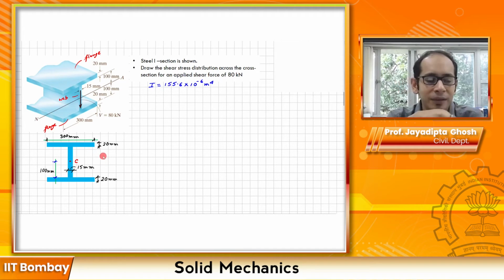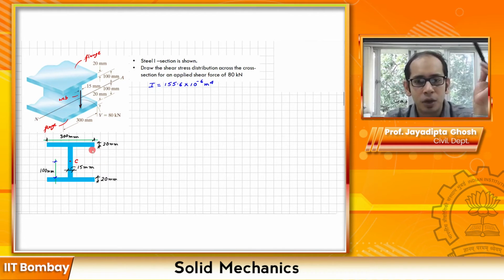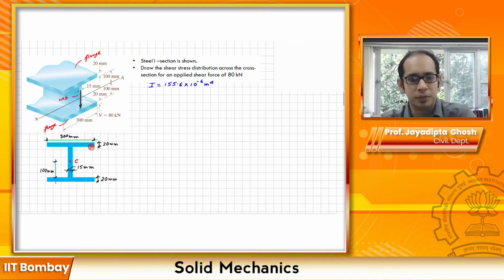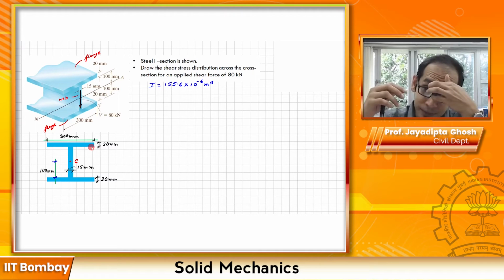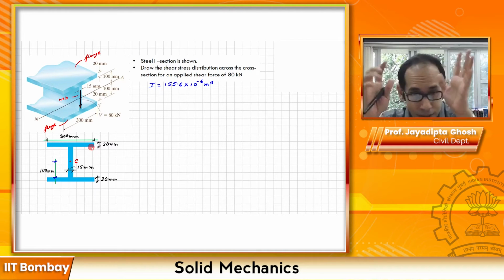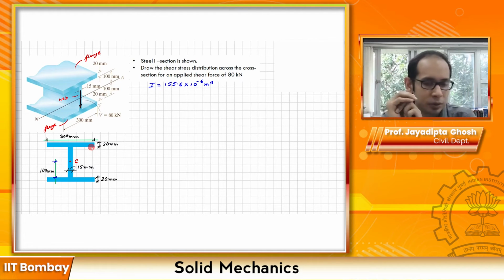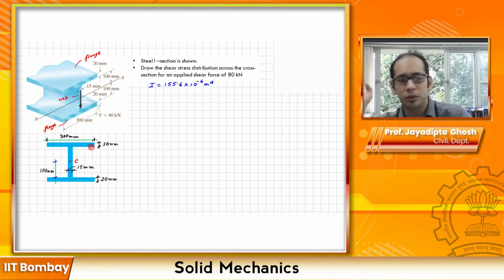Now that we have this figure, what are some of the key points of interest? Because we know a few things until now. The few things we know is that for rectangular cross sections, the stress distribution is parabolic, and it is maximum at the centroid, and at the edges it becomes equal to 0. So these are some of the things which we have derived.